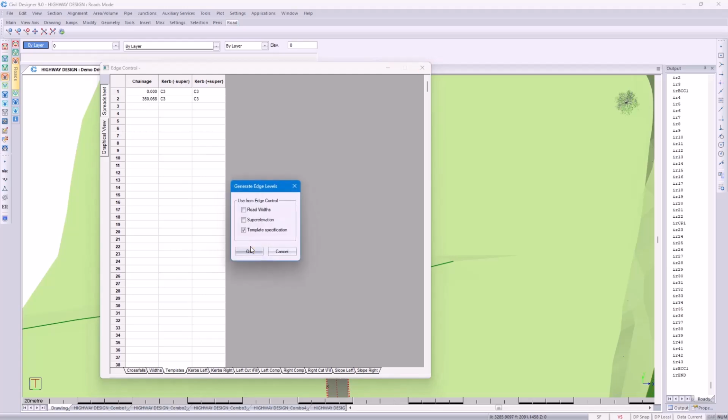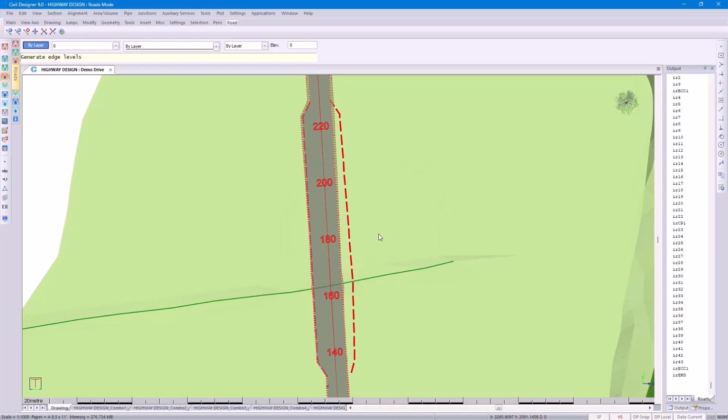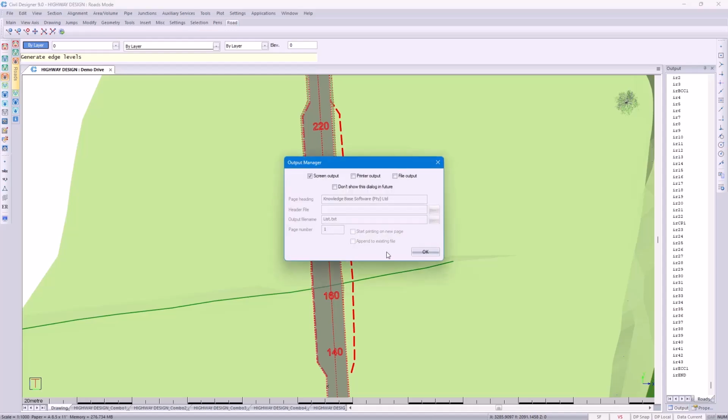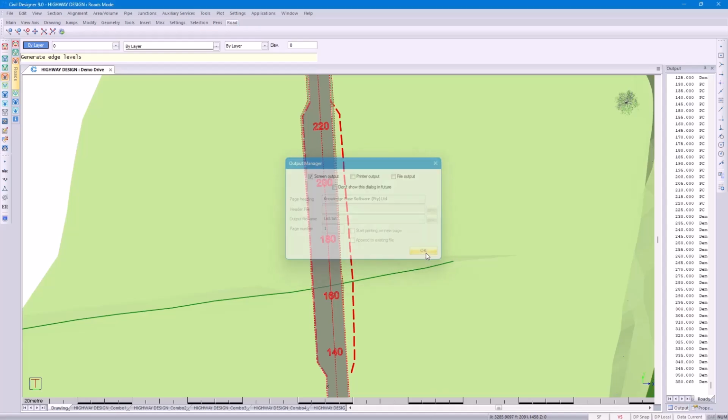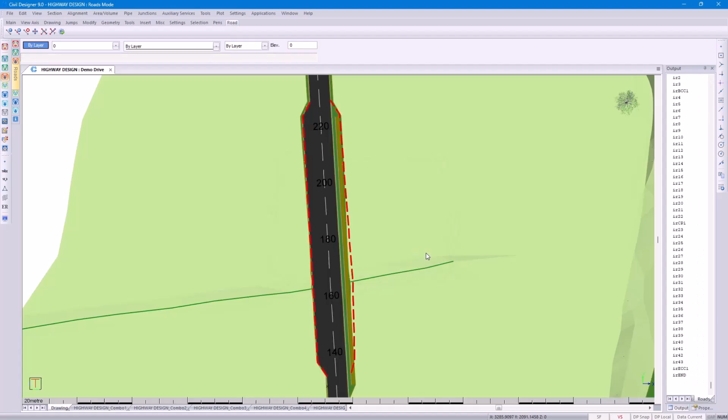Let's take a look at what that looks like before we actually apply the point control rules. Take a look at the plan drawing. It updates, but currently the V-drain will stay in the same position relative to the barrier. Let's take a closer look at this. I go to Section, Graphical Edit.